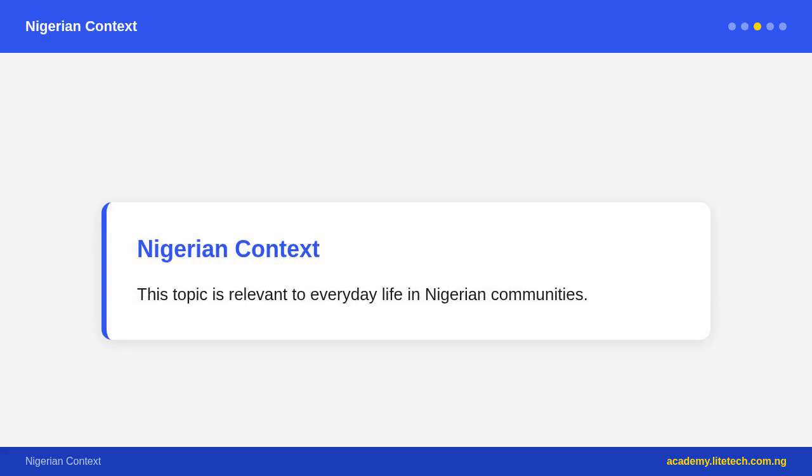UK mains, V_RMS equals 230 V. USA mains, V_RMS equals 120 V. Power in AC circuits, P equals V_RMS times I_RMS, for purely resistive loads. Since V_RMS equals I_RMS times R, Ohm's law applies with RMS values: P equals I_RMS squared times R equals V_RMS squared over R. These are the same formulae as for DC, using RMS values instead of DC values.